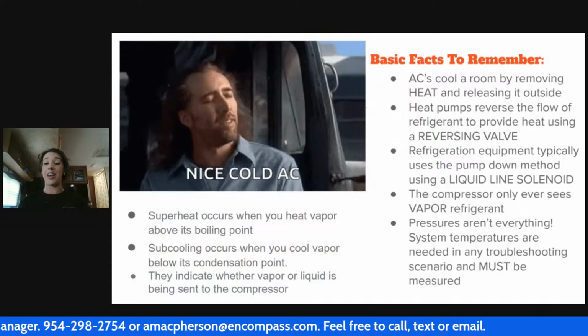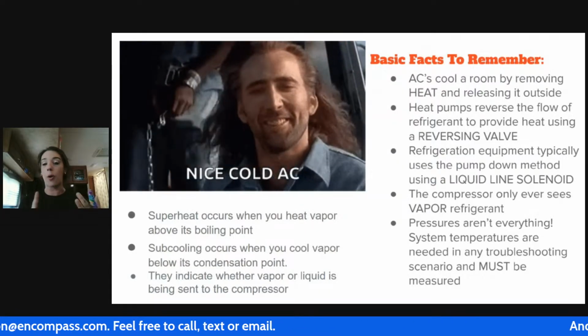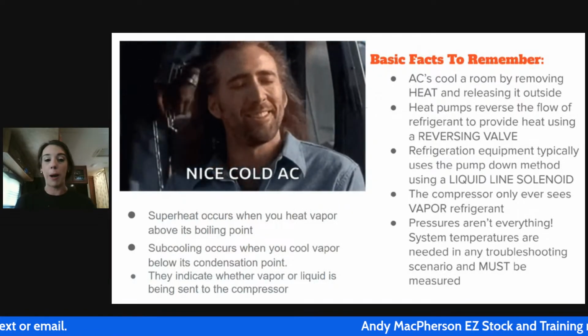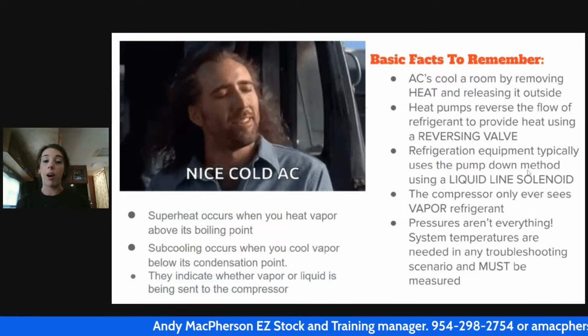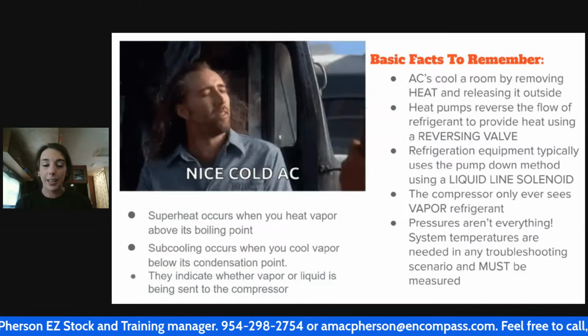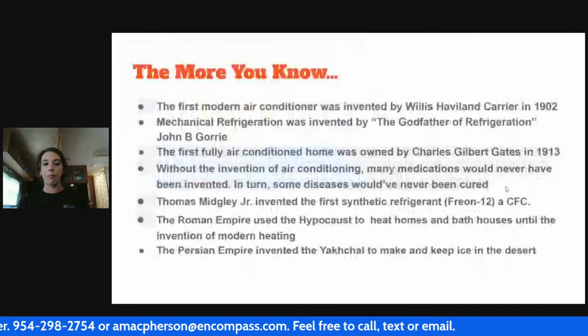But those are two of the three things it can tell us. And the third is just if it's broken. It can tell us that it's equalized. If it's out on thermal overload, or it's completely junk, or it's not turned on, pressures can tell us that by being equal. Those are the only three ways that those pressures are going to help you. Whereas these temperatures are all pieces to a puzzle that could have infinite outcomes. Make sure you're measuring. Please, please, please.